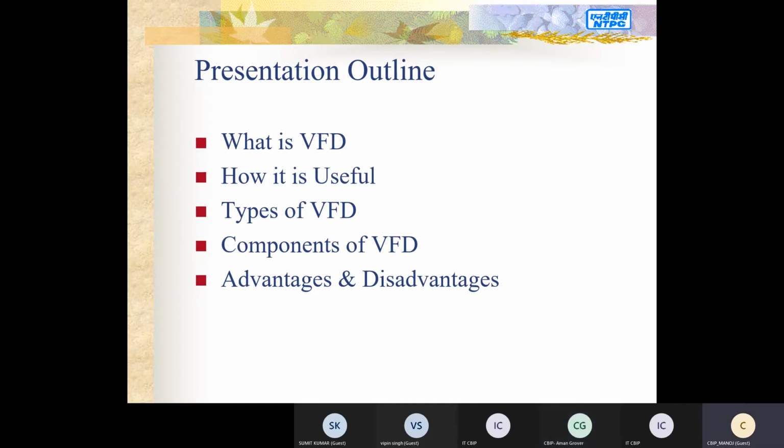No, basically we require speed control from the fluid side or for different mechanical reasons. Like suppose there is flow or there is pressure in the line, and you want to change the process parameters. So for changing these process parameters, we require speed control. You can do it from the pump side or you can do it from the motor side. It is always easier to do it from the motor side. Otherwise, we have mechanical means of speed control.